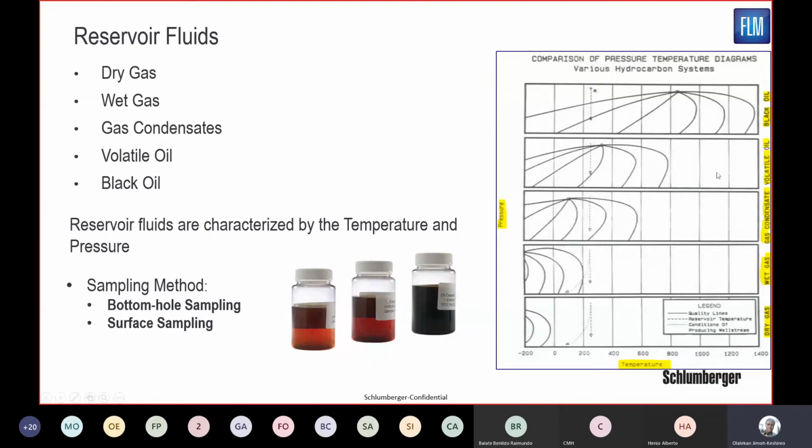On the side of this presentation, we see the phase envelope for the different characterizations of the fluid, right? And one major thing, just like any thermodynamic substance, you define the state of such a substance by knowing the temperature, the pressure, and the volume it exhibits at those conditions. And hence the word PVT: those are the key parameters that actually determine the state of the fluid, which is also the driver in classifying them by the behavior of their phase envelope.